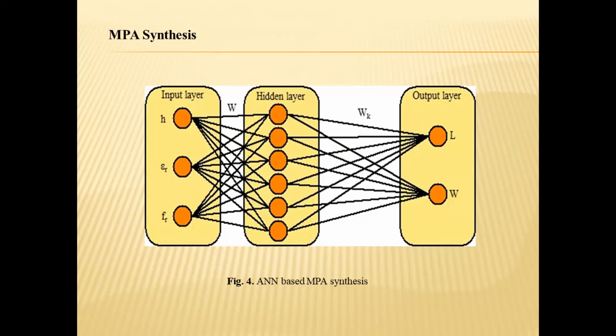Here, different algorithms like GDNN, ANN, RBF, LMANN have been explored extensively due to the ability to process large sets of input data in low computational time. For microstrip patch antenna synthesis, we applied different variants in addition to the proposed AGA-ANN model, where we feed the cutoff frequency parameter, dielectric constant, and height of the dielectric as input to obtain the two optimal values of the patch length and patch width.